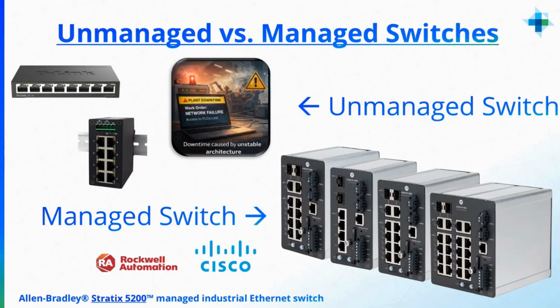Now, managed switches, on the other hand, allow us to configure and prioritize network traffic, giving priority to devices like PLCs, HMIs, and drives. The Stratix 5200 specifically is an optimized industrial switch developed by Rockwell and Cisco. Industrial managed switches like the 5200 also include security features, diagnostics, network segmentation, monitoring, and faster troubleshooting.